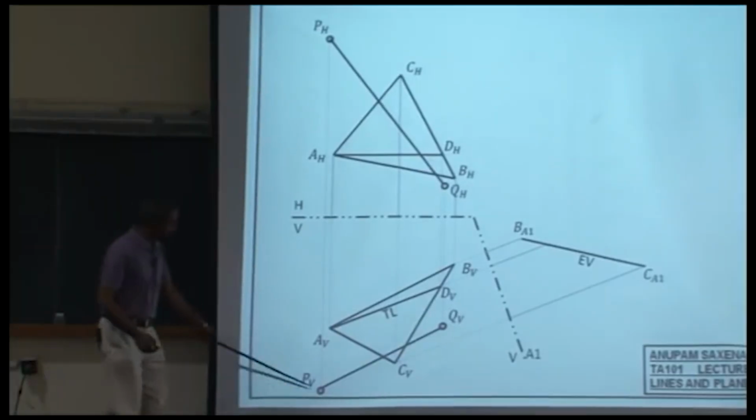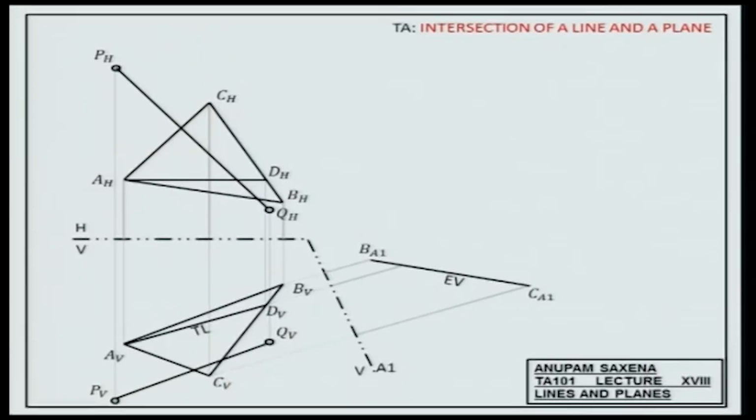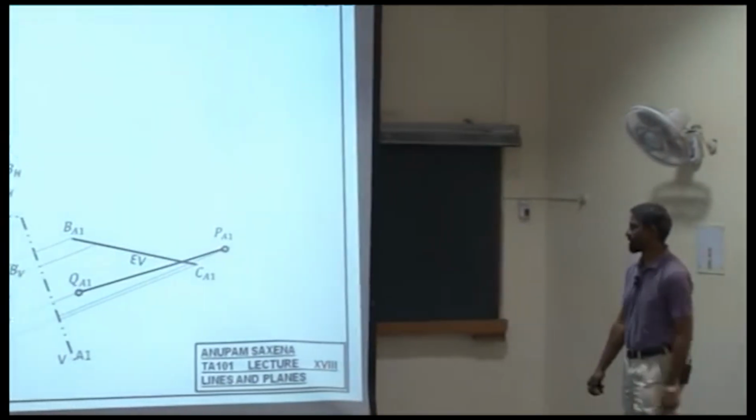You have the corresponding projection points over here, P and Q. Shoot the projections out, measure distances, transfer it down there. So that's your PA1, measure that distance, that's your PA, that's your QA1. Okay? So this is what you see in the edge view auxiliary plane of that plane, of course.